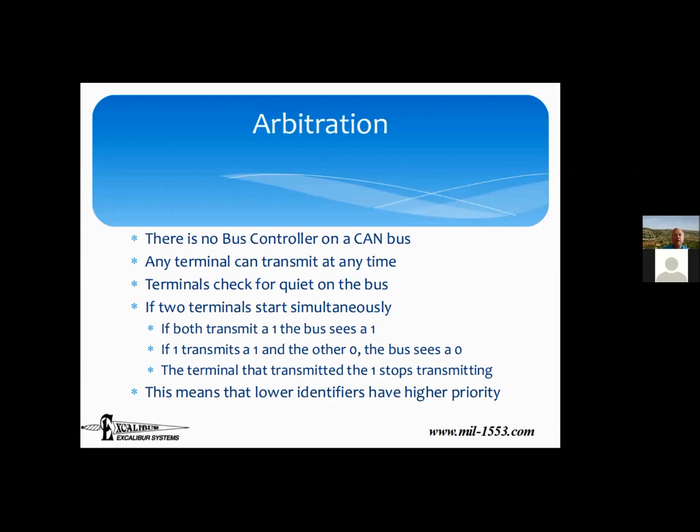However, in CAN bus, it doesn't work that way. There are no switches in CAN bus. Everybody's connected to the same bus. And all of them can transmit whenever they feel like it. I mean, there's a schedule in terms of how frequently they're allowed to transmit. That's what we saw in the minor frame thing. But that just says that if they transmit, they now have to wait a certain amount of time before they transmit again. But it doesn't coordinate them with anybody else.